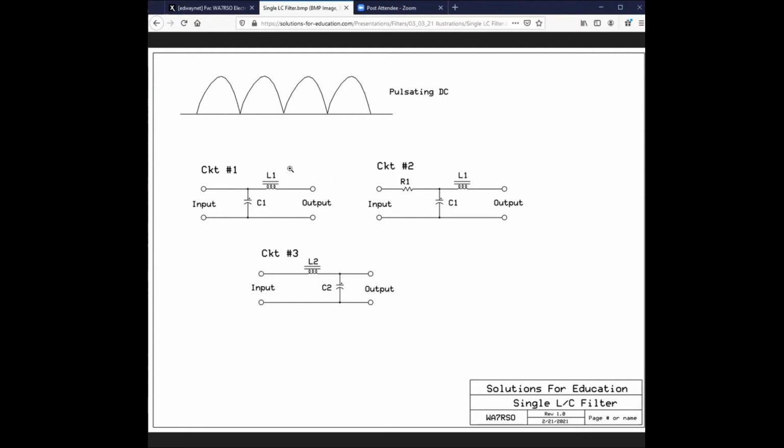Now, I'd like to back out of this for just a minute and do something else. Electrical safety. There's something that not everyone knows, and I will assume that you guys probably do, but nonetheless, I want to put it in here for the record. 60 milliamps is enough to cause severe cramping, so you cannot let go. 100 milliamps, I'm talking about arm to arm, hand to hand through the trunk, can be lethal. They consider that 200 milliamps through the trunk is lethal.